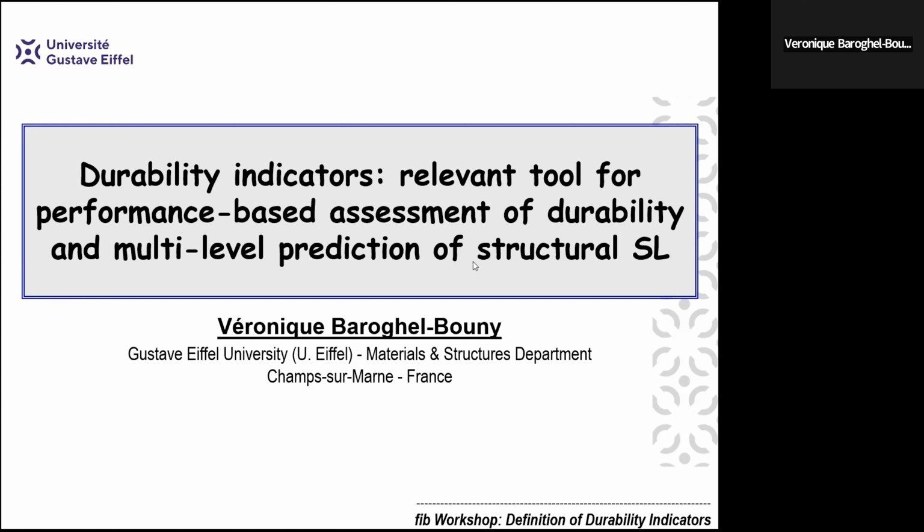And in the carbonation model, I have an example in the presentation, you need both. If you come back to Papadakis' model, which is very famous and very simple, you need both Portlandite content and CSH content. So anyway, you need something to put in your models in this case, and it depends, of course, on the process.